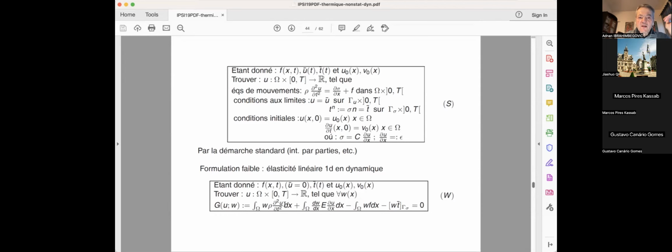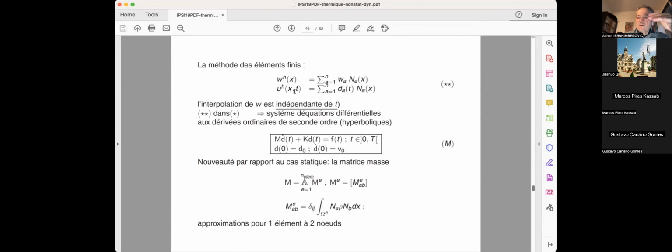That means at the frozen value of time, you are imposing the infinitesimal kinematically admissible displacement field, which is then testing equilibrium by saying the work of internal forces, that is the stresses, and the work of external forces, including inertial effect, have to match each other. So w, because of that, is just function of x, because t is frozen, whereas displacement field, which is function of x and t, is done in this spirit, which means that we are really imposing a solution which would imply the separation of variables.